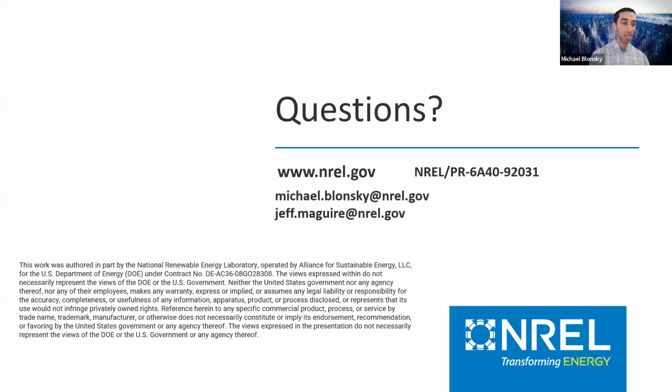Jeff, I'm going to give you the first one. For building characteristics, are you assuming those are known based on the home details, or do you have some parameter identification that can be done without details of the specific building? Yeah, good question. So we are generally assuming that these are known characteristics because we are trying to keep this as a fully white box based model, rather than trying to fit to measured data, which would be more of a gray or black box based approach. So we are generally assuming that we know things about the constructions, the type of HVAC equipment, those sorts of things that can have a big impact on energy consumption.